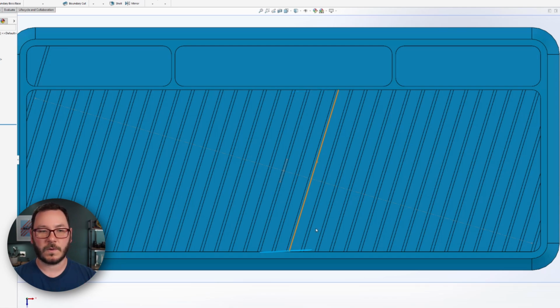So it's going to find its way all the way up and down, but it's a little bit harder to visualize what's going to happen to this sketch as it gets way out here. And you can see in this case, this sketch was maybe here, this endpoint ending here. It's now looking for its new bounds, which it finds to be up here. So it now continues all the way up and finds the correct bounds down here. So this is something that we have to be conscious of, especially when we're patterning this over long distances.